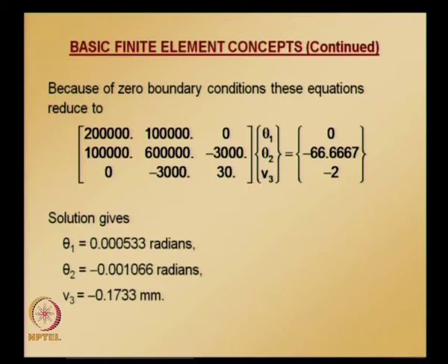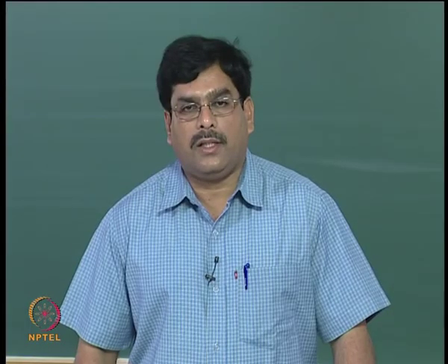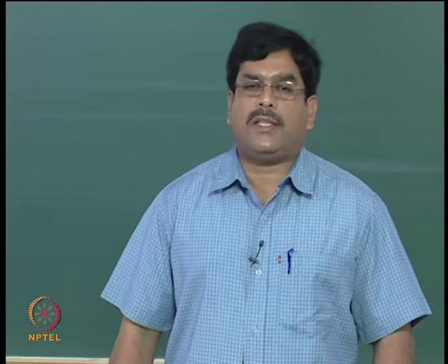So, now we are ready to go to each element and solve for element quantities: the bending moment and shear force in element 1, and the bending moment and shear force in element 2, since we got the nodal values. The only thing is, on element 1 there is no load applied, so we do not need to apply fixed end moment correction when calculating moments and shears.